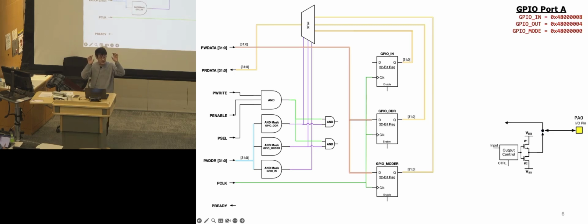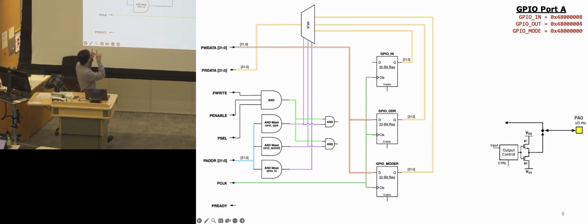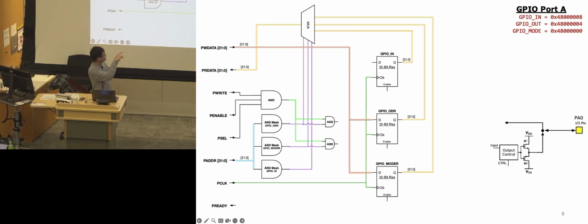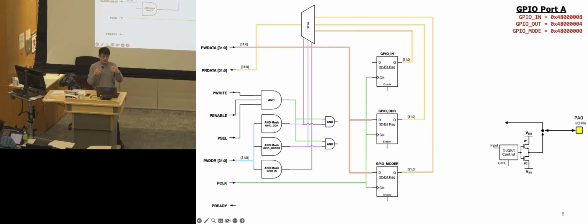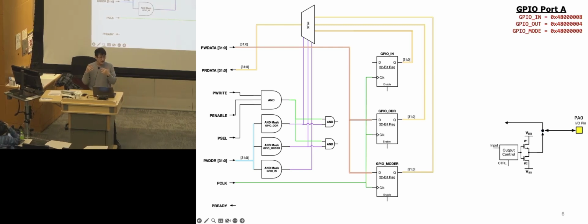Whatever signal is sent to that peripheral is shared by all these registers. So the p-select pin will be shared with all those that have the capability to connect to that pin. So we need something additional to know exactly which register needs to be activated, which is what the p-address is needed for here.